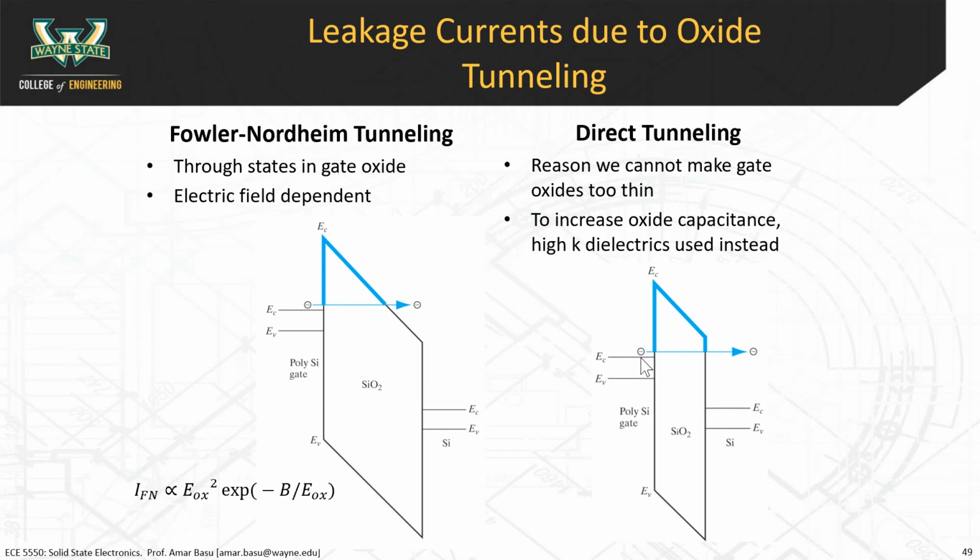Yes? So does having the body effect increase your chances of having this first type of tunneling effect as well? So the question is, does the body effect increase the probability of tunneling? And what's your thought process behind that? Well, I think that with the body effect, you're always increasing the electric field. Basically, that's why you have such an issue overcoming your problem there with the body effect. So I would think that you would be more likely to have issues with tunneling.